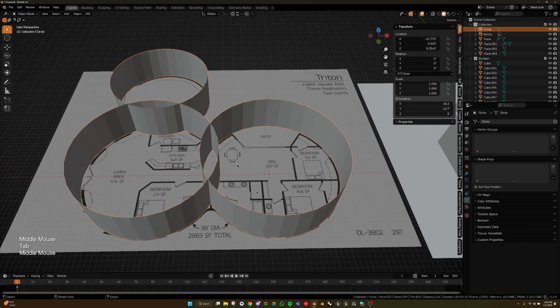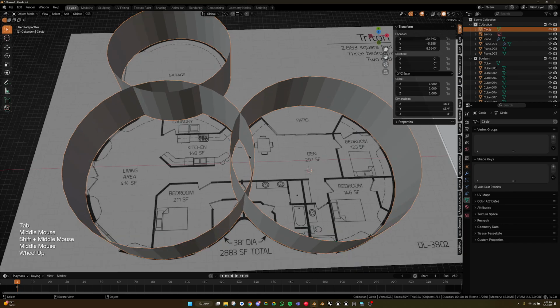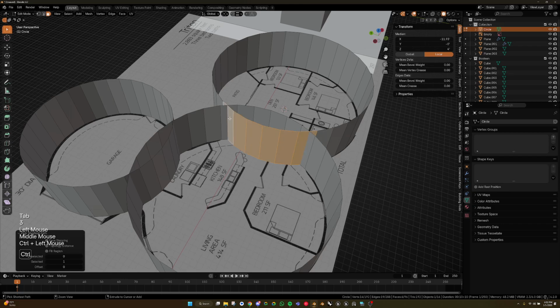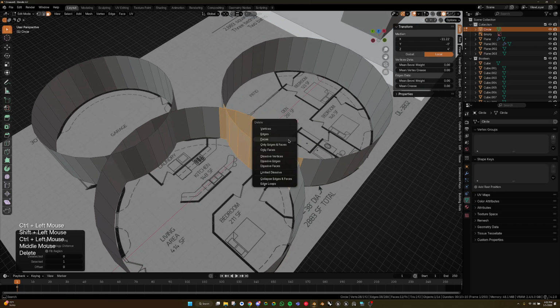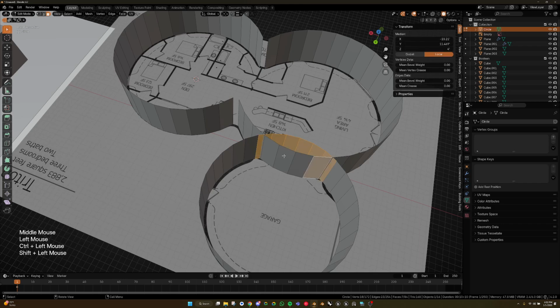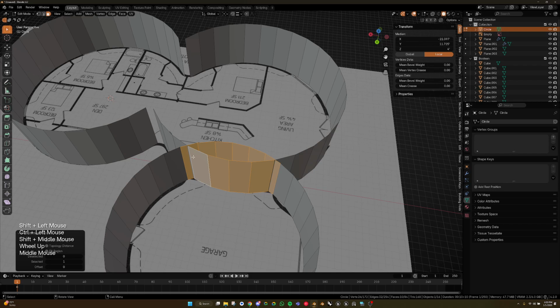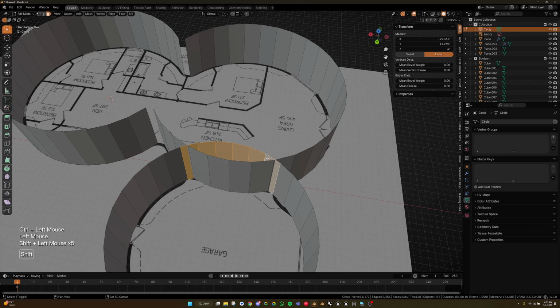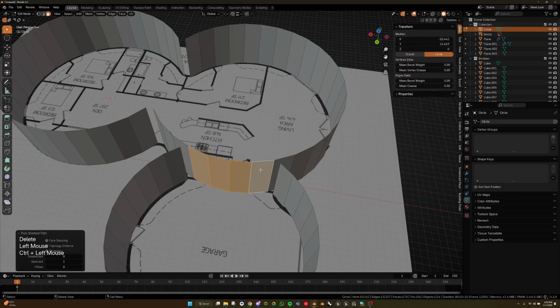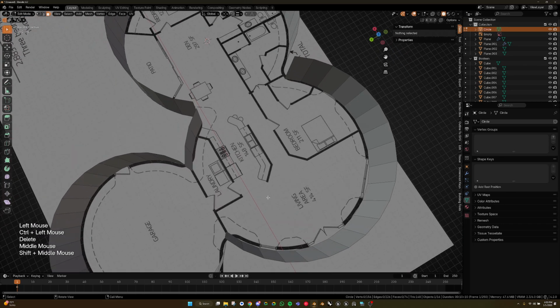Like that. So there's our walls. To create a connection here, we're just going to remove these faces, right? Just remove them. And then for these as well, you're just going to remove where they're overlapping like that. By the way, I'm clicking here and holding Control, so I don't have to select each one individually. I could just hit the start and end, and it connects the faces in the selection. Boom, boom, delete. Something like that.